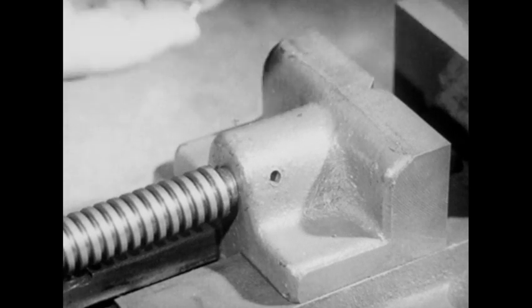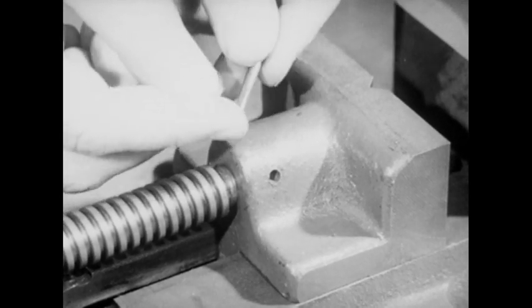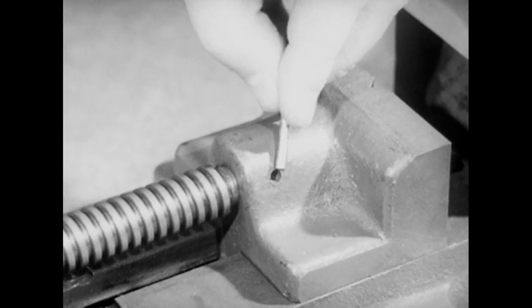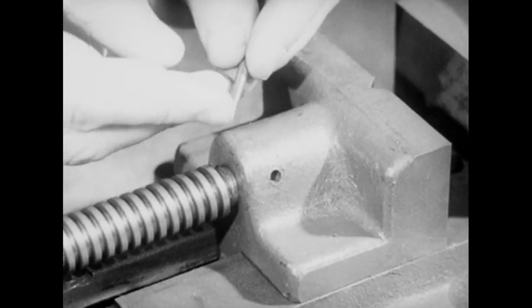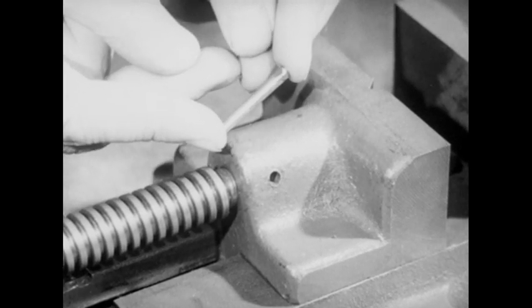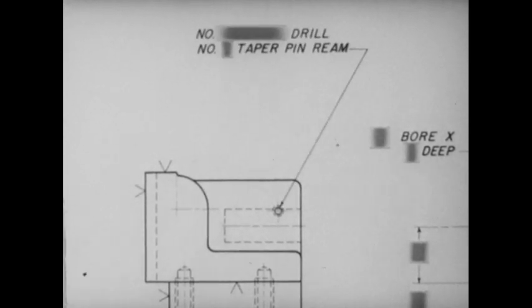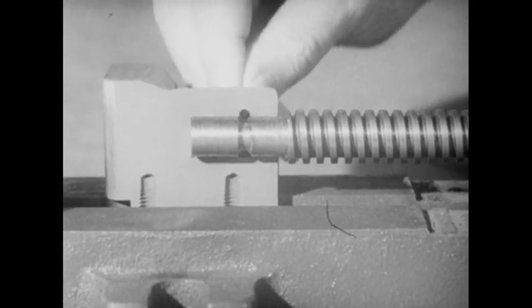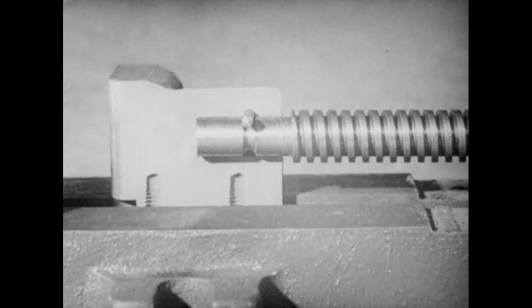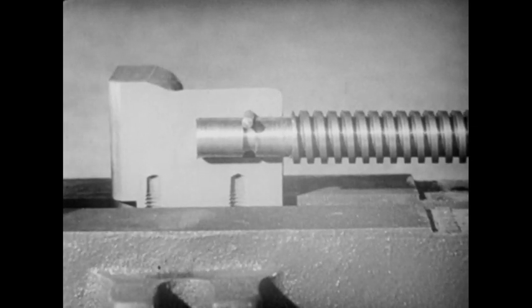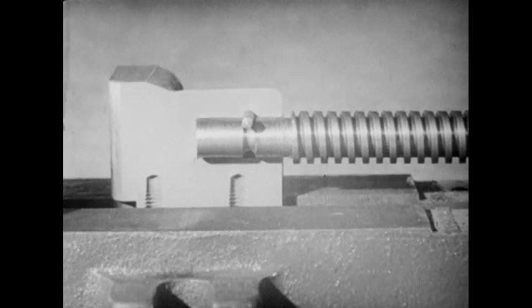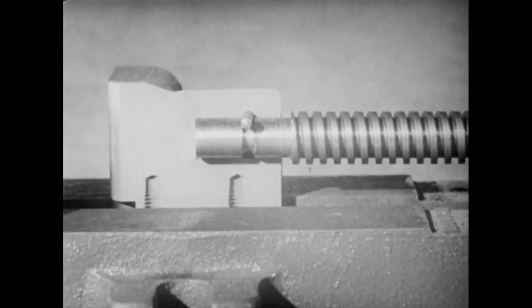The taper pin, which keeps the cylinder from coming out, must fit with its mating part, the taper pin hole. The hole will be drilled and taper reamed to fit the pin, which is a standard taper. Give the dimension as a note to drill and ream. Here is a case where the choice of dimensions is governed by the shape of the mating part. The taper pin fits in a groove in the shaft. Notice again how the shaft pushes on the bottom of the hole. On the return move, it is held in place by the groove, which fits around the taper pin.